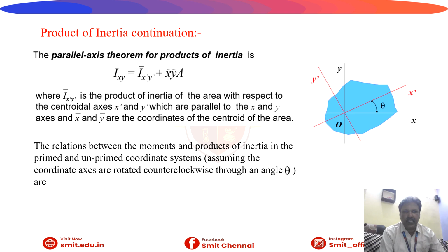Ixy equals I bar x dash y dash plus x bar y bar A, where I bar x dash y dash is the product of inertia of the area with respect to the centroidal axes x dash and y dash, which are parallel to the x and y axes, and x bar and y bar are the coordinates of the centroid of the area.